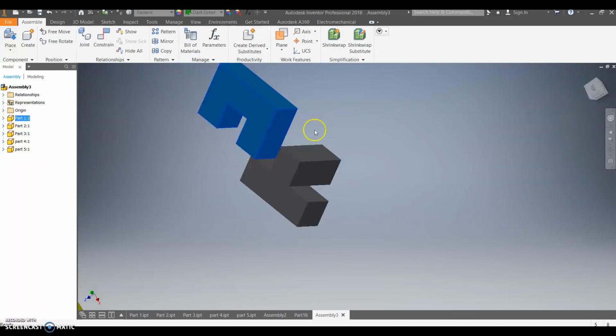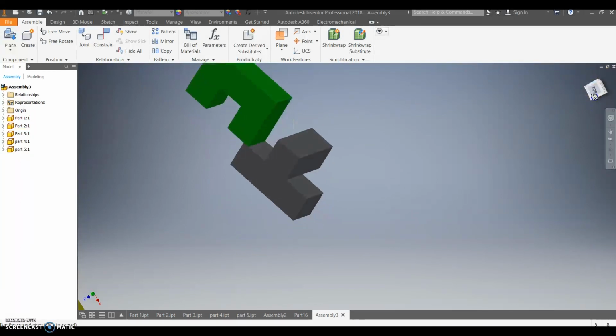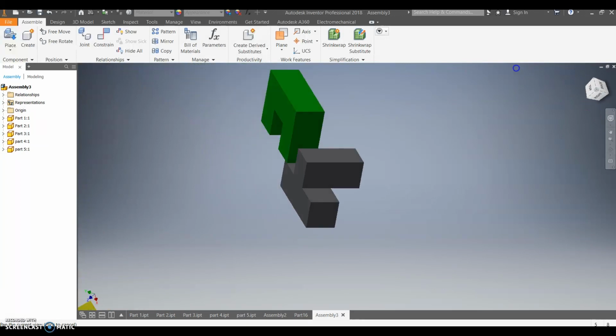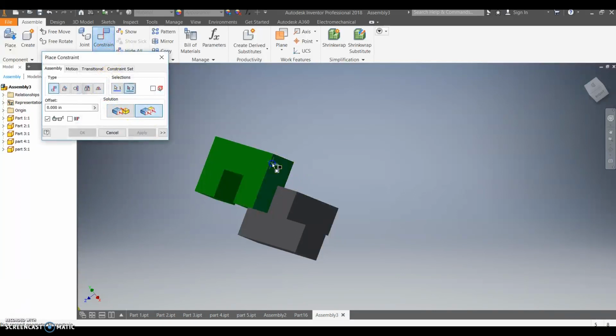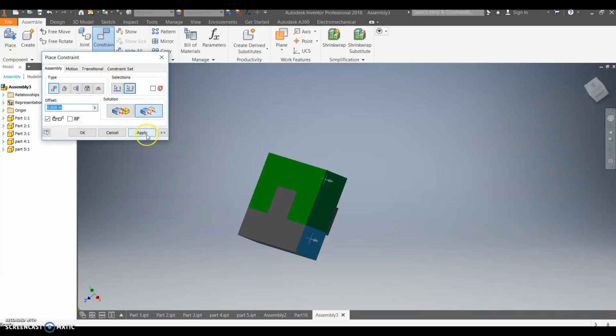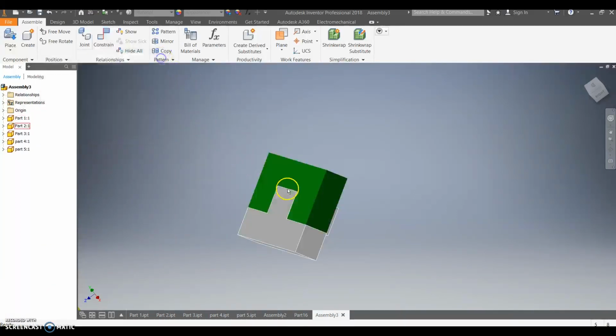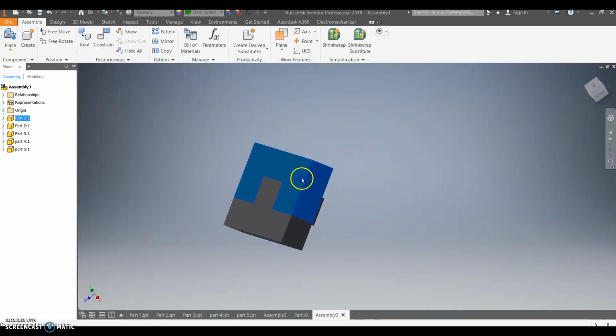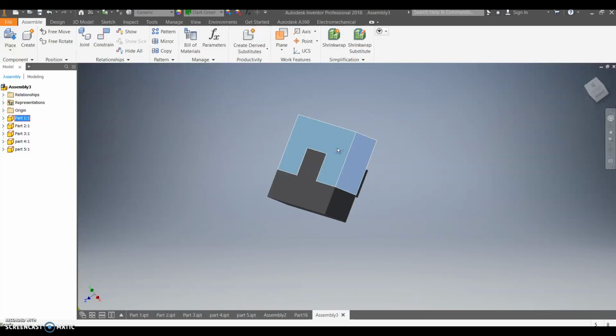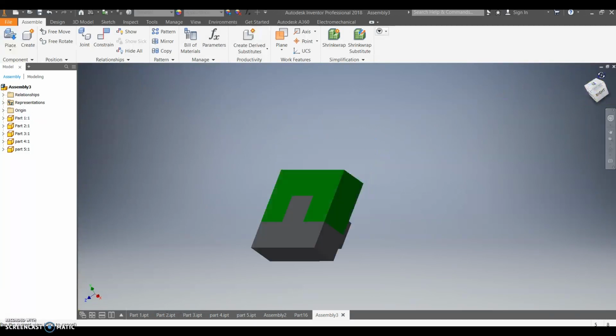But it's much easier than trying to rotate to this side to see the inside there and the outside here. I'm just going to choose the flush constraint again. One thing I make my students do is I always make them grab one part and move it and see if anything comes apart. That will determine whether or not the part is fully constrained.